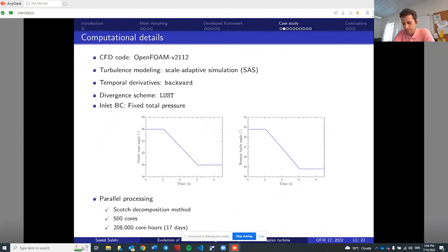Okay. And did you also consider changing the rotational speed of the turbine itself as a third parameter that you can tweak in partial load? Is that a topic for you? Yeah, that is actually on our to-do list. But the thing is that we are working with the experimental facility on this specific test case, on the experimental measurement. In the transient operation of this turbine, the turbine is always connected to a generator, so the rotational speed is always constant, even when we go into the deep part load. So that's not something that we want to do specifically for this procedure, but still it's on our to-do list to add to our framework.